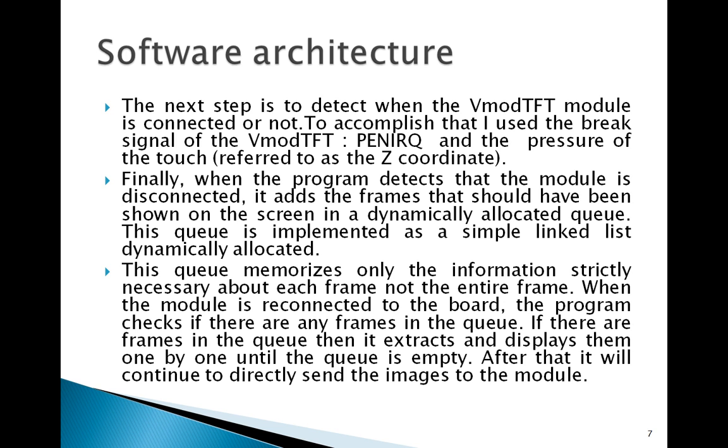The next step is to detect when the VmodTFT module is connected or not. To accomplish that, I use the break signal of the VmodTFT called PenIRQ and the pressure of the touch, referred to as the Z coordinate. Finally, when the program detects that the module is disconnected, it adds the frames that should have been shown on the screen in a dynamically allocated queue.